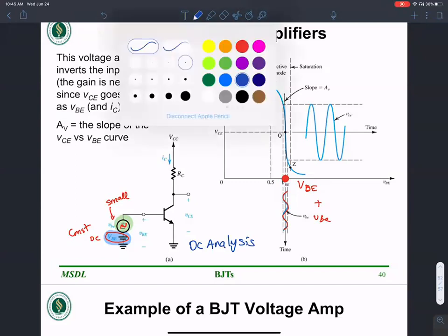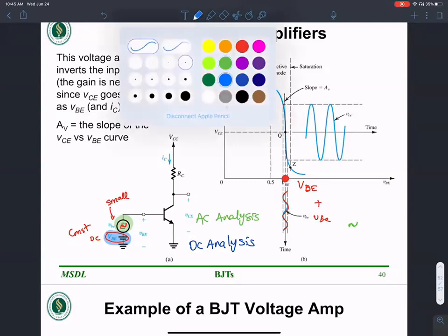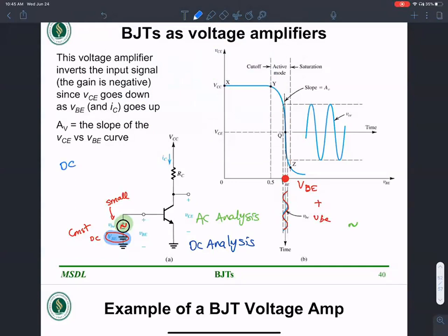Okay, and then we want to do the AC analysis as well. By linearizing, what I mean is the argument goes, if the AC signal is so small, then what is supposed to be a non-linear relationship can simply be converted to a superposition. Okay, that is what the general procedure involves when you do the analysis. Okay, you first do just the DC analysis without AC, VB equals little vb equals 0.